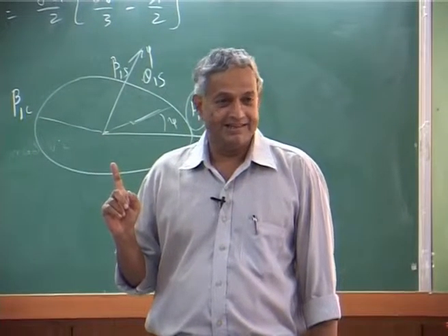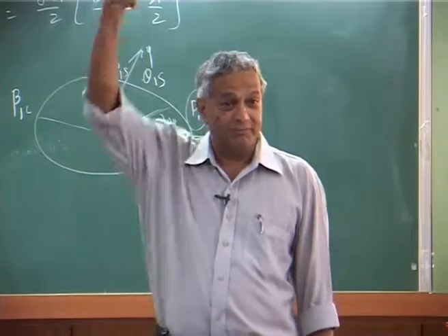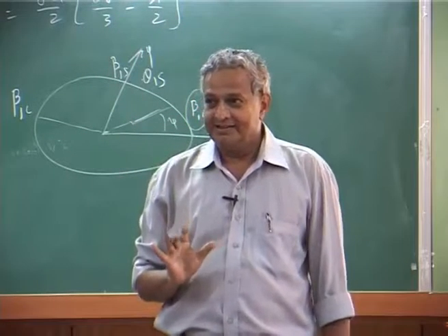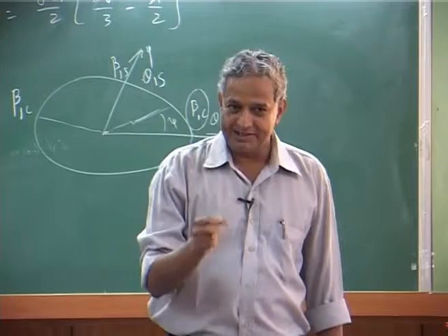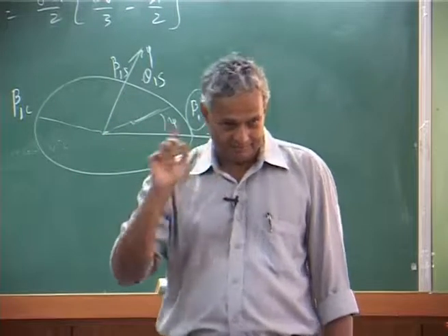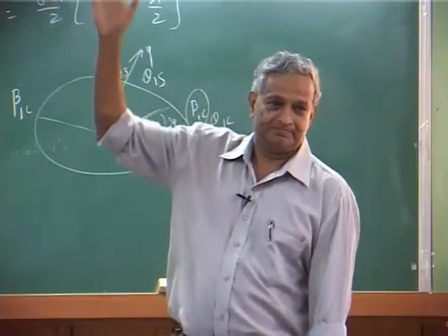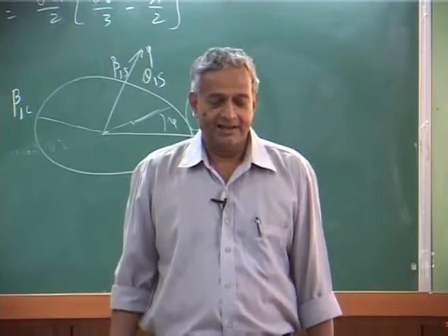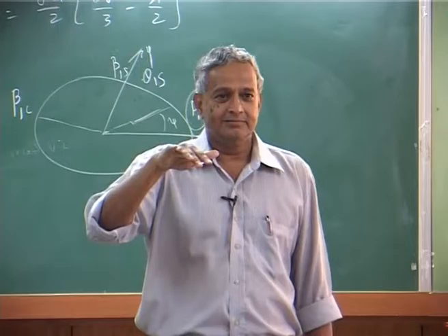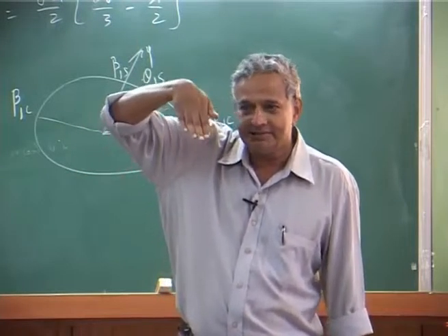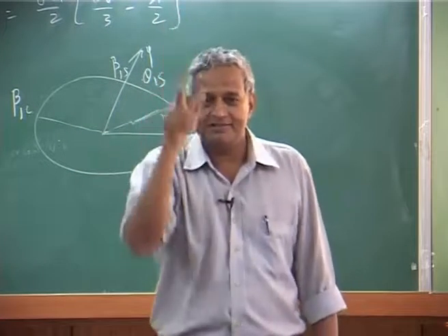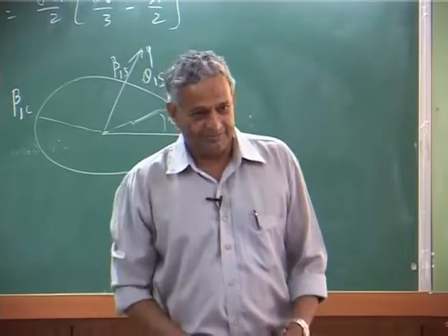He is not giving a flap response, he gives a pitch input. Because of the pitch cyclic variation, the blade flaps, and the net result is the rotor disc tilts forward. So, he gets a thrust in that direction.